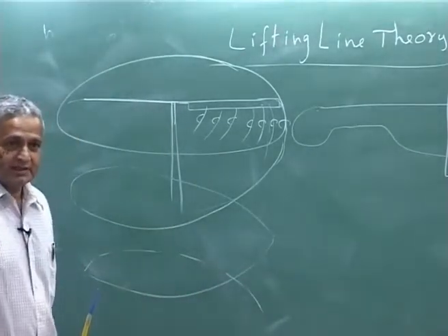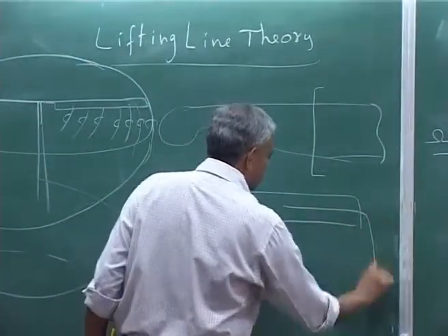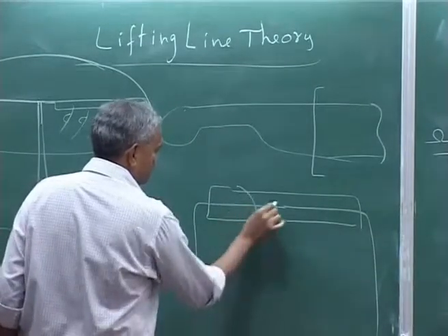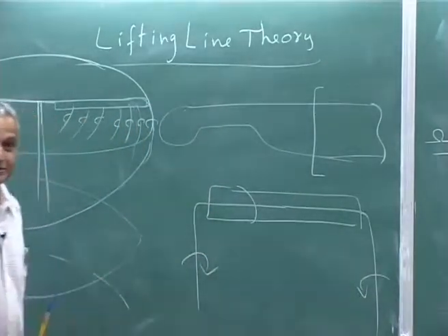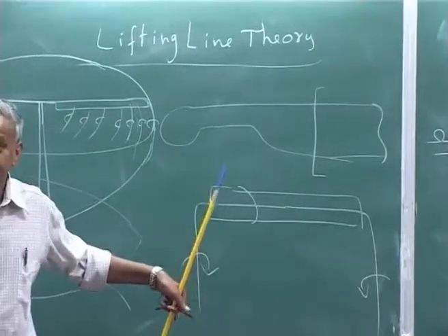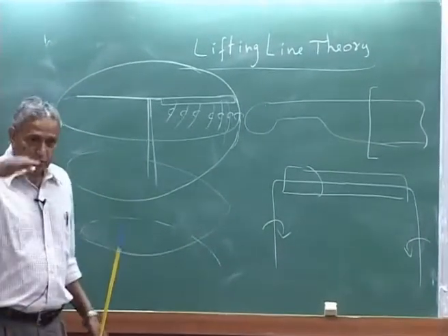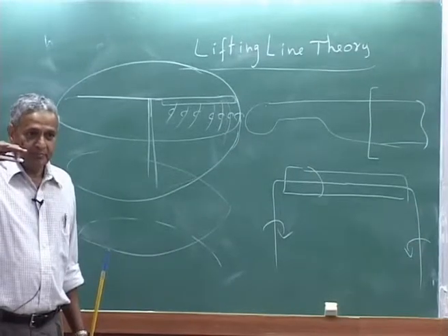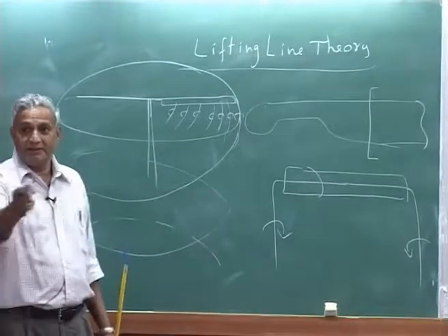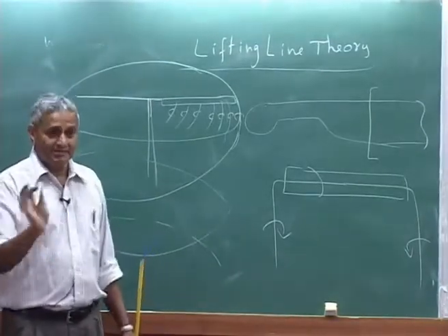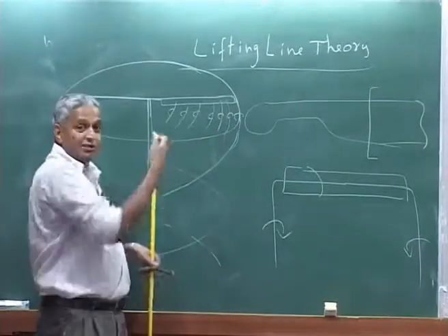Because in the finite wing case, you will say my vortex sheet is going like the horseshoe vortex, because this is what you say. This is a horseshoe vortex in a finite wing. The vortex is swept back. But in the case of a rotor, a hovering rotor, the vortex is piling below it. It will go in a helical path, because as it goes around it leaves, and this one is pushed down by the induced velocity by its